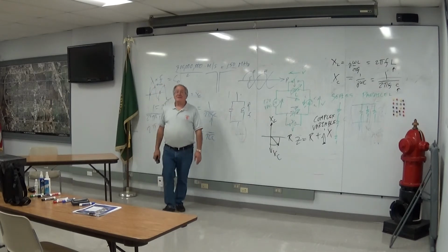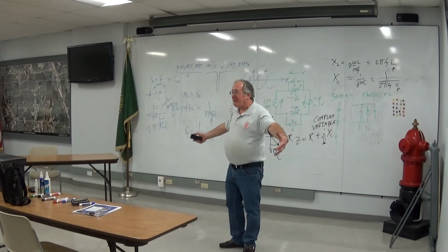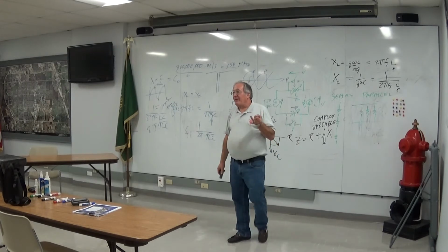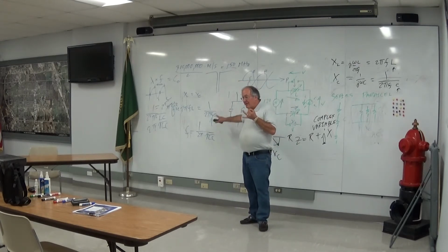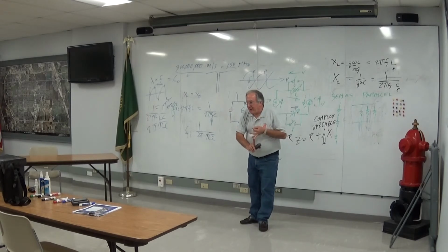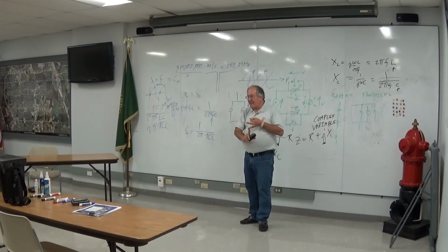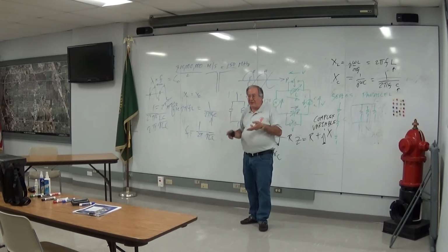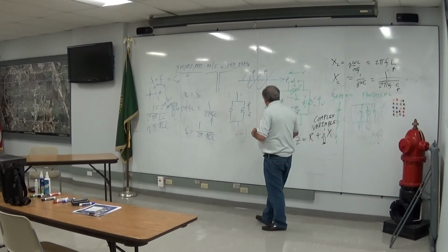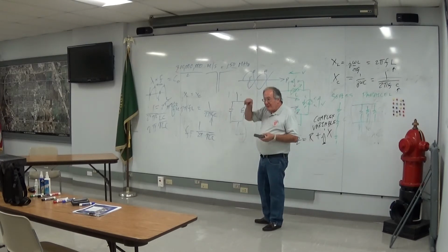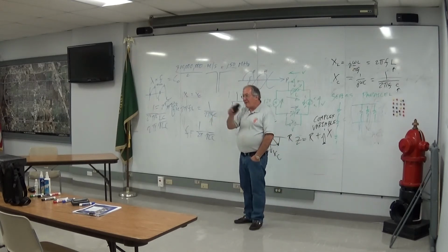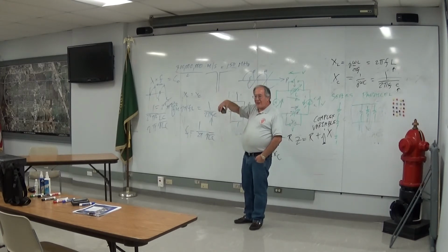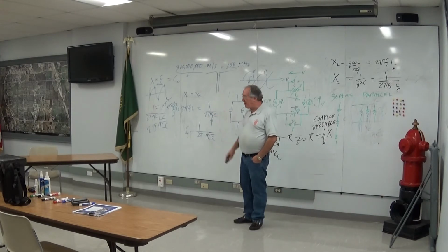Next week, I will finally give you something that you can put your teeth into. We're going to build a circuit. We're going to actually put some electronics together. We'll build a power supply, which has a transformer that uses inductors. It will have a rectifier, which turns AC into DC, and is nonlinear, and has that feature we call the semiconductor effects. We will have a filter network that uses a little bit of this, a little bit of that, to take all the ripple out of the converted DC that came from AC, and we'll introduce you again to the transistor, which will regulate the voltage so that you get the same voltage whether you draw a lot of current or a little current from it.